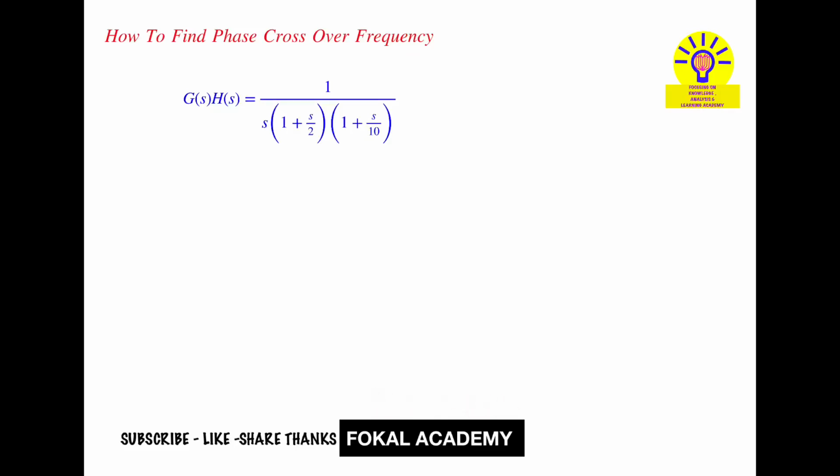See this problem. Here the open loop transfer function is given, that is G(s)H(s). Now how can you find the phase crossover frequency for this function? This is the problem. So first of all, what is phase crossover frequency? Whenever you find the phase angle for the given function, that is the phase angle for G(s)H(s), if you get minus 180 at a certain frequency, that frequency is called the phase crossover frequency.